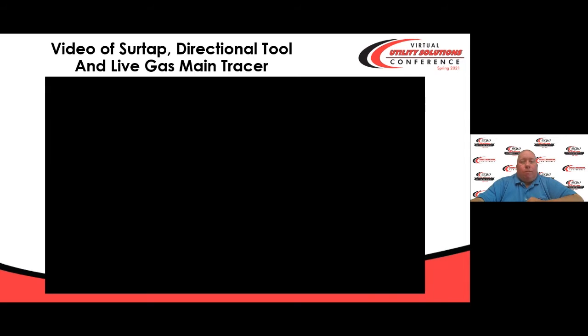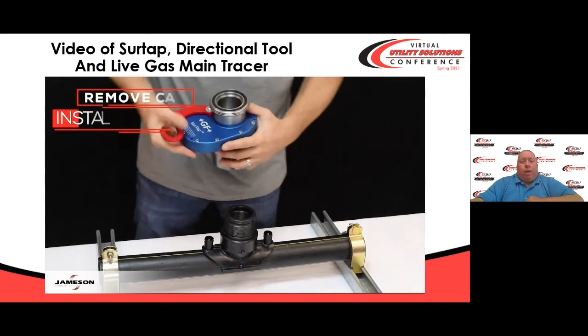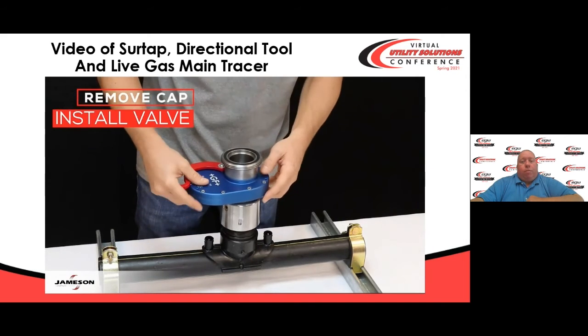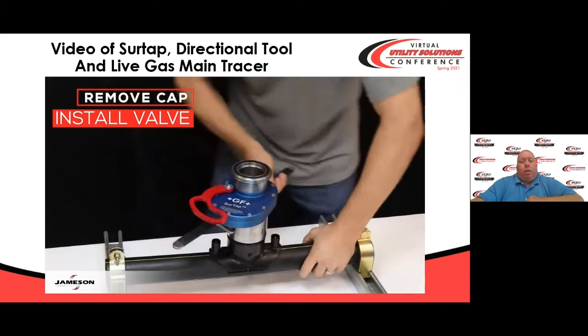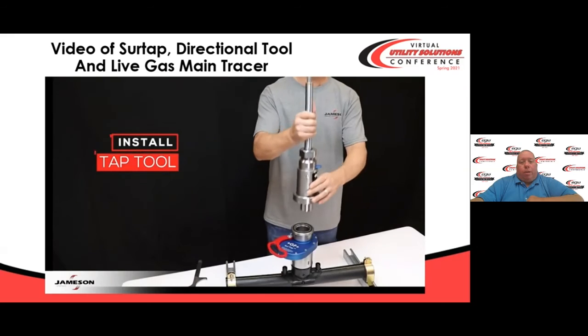So now we're going to look at a short video that shows how the VersaTap fitting, SureTap tapping tool, directional entry tool, and mainline tracer are all used. Let me play this for you, and I may talk over it a little bit from time to time. So you can see they start with the fitting there. They remove the cap and the completion plug, thread on the valve. Tighten the valve with the provided wrench.